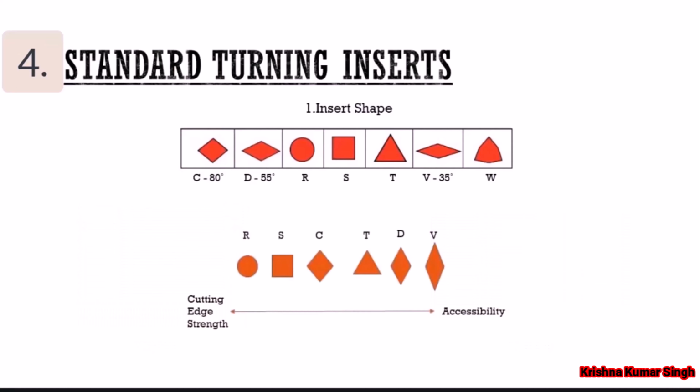At this point, before moving forward, I want to talk about different types of operations like roughing, finishing, continuous cutting, and interrupted cutting. To convert raw material into a final product, many operations are involved, such as roughing and finishing operations. A roughing operation, generally speaking, is used to remove a large amount of material quickly and to produce a part geometry close to the desired shape.